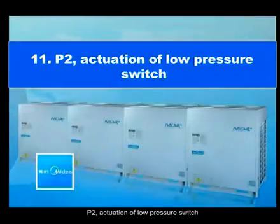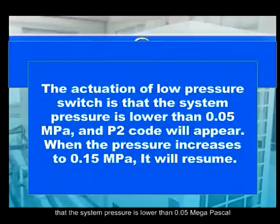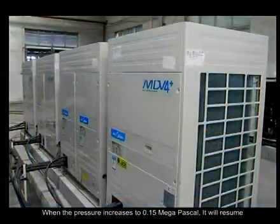P2. Actuation of low pressure switch. The actuation of the low pressure switch is when the system pressure is lower than 0.05 megapascal, and the P2 code will appear. When the pressure increases to 0.15 megapascal, it will resume.